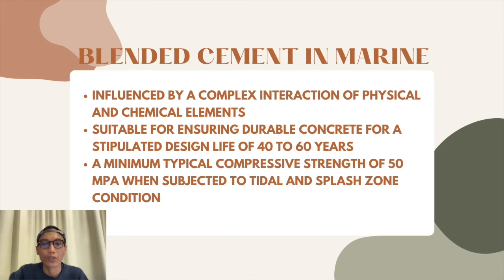The performance of concrete in maritime construction is influenced by a complex interaction of physical and chemical elements. The present specification of Australian standard AS3605 is suitable for ensuring durable concrete for a stipulated design life of 40 to 60 years. When the structural member is subjected to tidal and splash zone conditions, this standard prescribes a minimum typical compressive strength of 50 MPa.